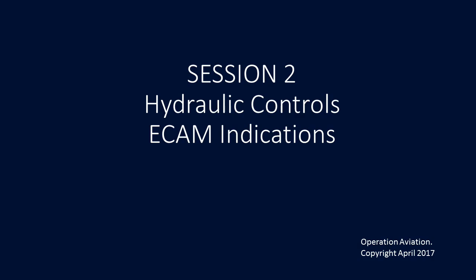All right, what about engine 1 and 2, your fire push buttons? These switches are on the overhead. These in particular are on the 20 VU, and they're controlling the motorized valves in the suction lines to the engine pumps.